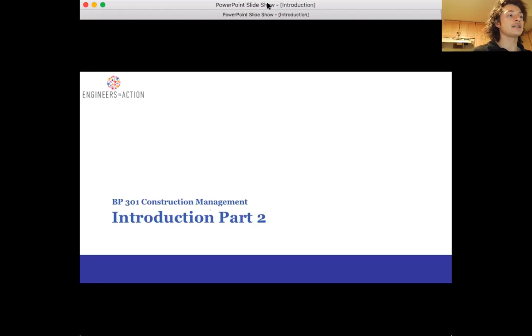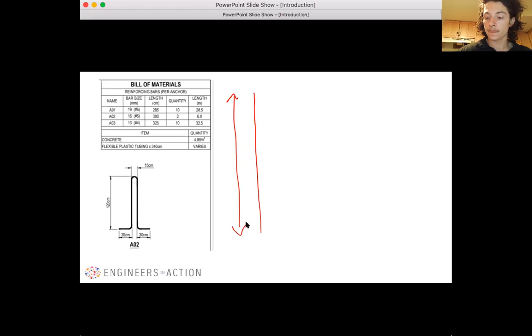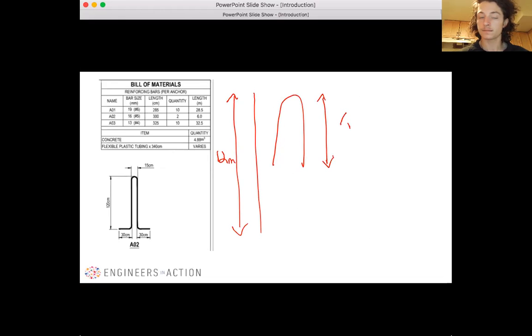For example, imagine you are in country and pick up a 12-meter length of rebar. In order to transport this piece of rebar to site, you bend it into approximately two 6-meter pieces to fit into the truck. When you arrive on site, there is no way to unbend the rebar, so you now cut the bend off and have two sections of 5 meters left over for use.